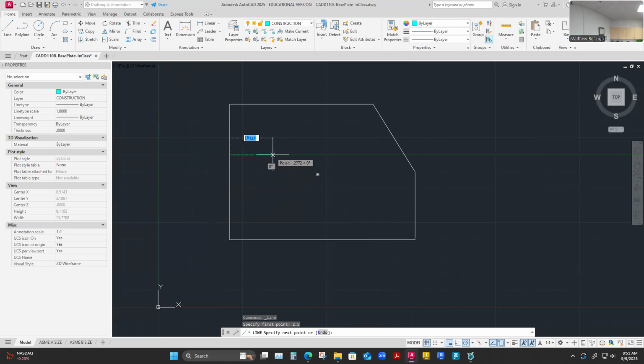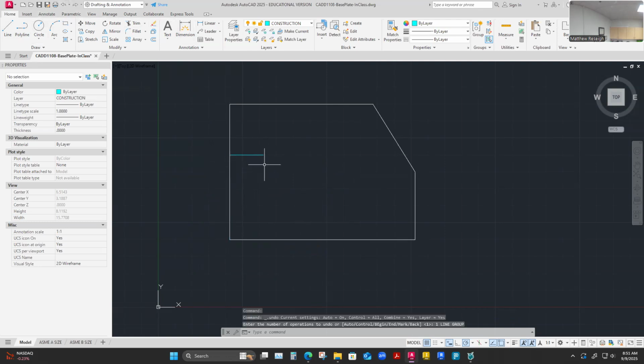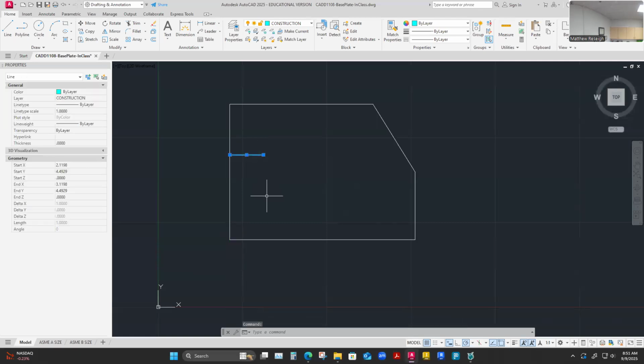And then it's 1 inch over in this direction, right? 1 inch. So it wouldn't have been wrong if you would have drawn a line like this up to here and then drawn over like that. That would be totally fine if I had a line structure like that on a different layer. So if that works for you, that's fine. I'm going to undo that and just use the one line I placed. So this is now 2.5 inches up and 1 inch over. The endpoint, that grip, is going to be the center of my circle.